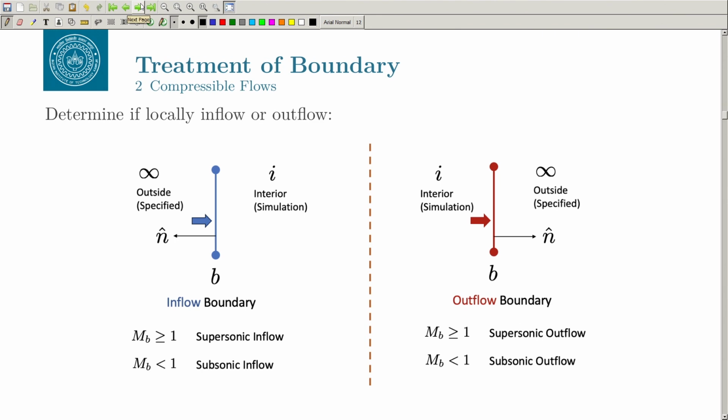Now, the compressible flow is slightly tricky. If you say compressible flow, your flow can be subsonic, supersonic, maybe hypersonic, transonic. There are different regimes, and flow phenomena change depending on which regime you are in. In the subsonic regime also, it can be very low subsonic or high subsonic. In the subsonic, it is typically a Mach less than 1, but let us say Mach less than 0.3.